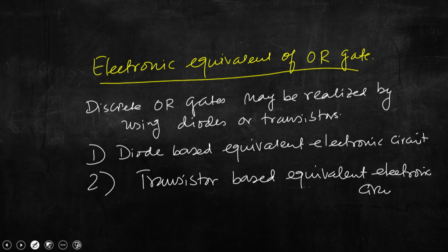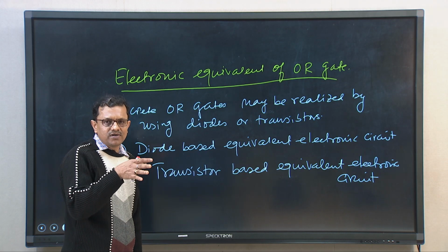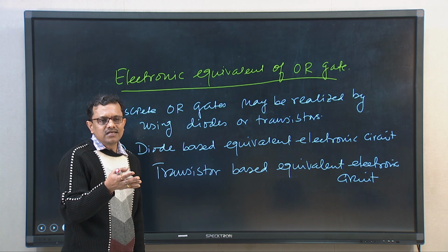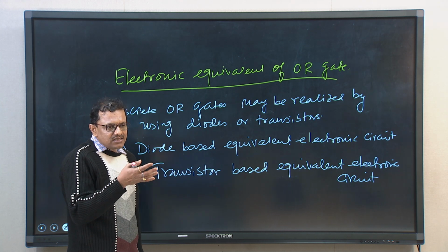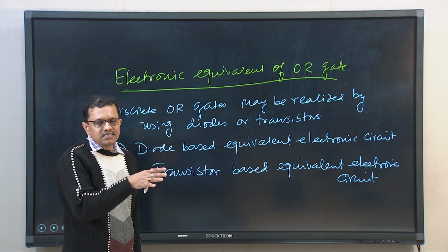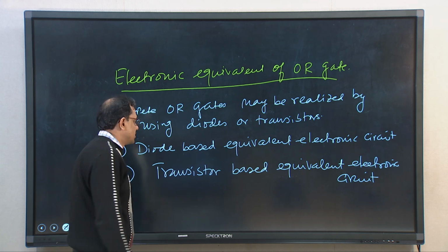electronic circuit. We are discussing all these because essentially the signal that we will be receiving from different parts of the engine is an analog signal. That signal should be converted into a digital one, that is in the form of 0 and 1. Then this digital circuit will give some input again to all those parts to adjust so as to operate the engine always at its optimum condition.